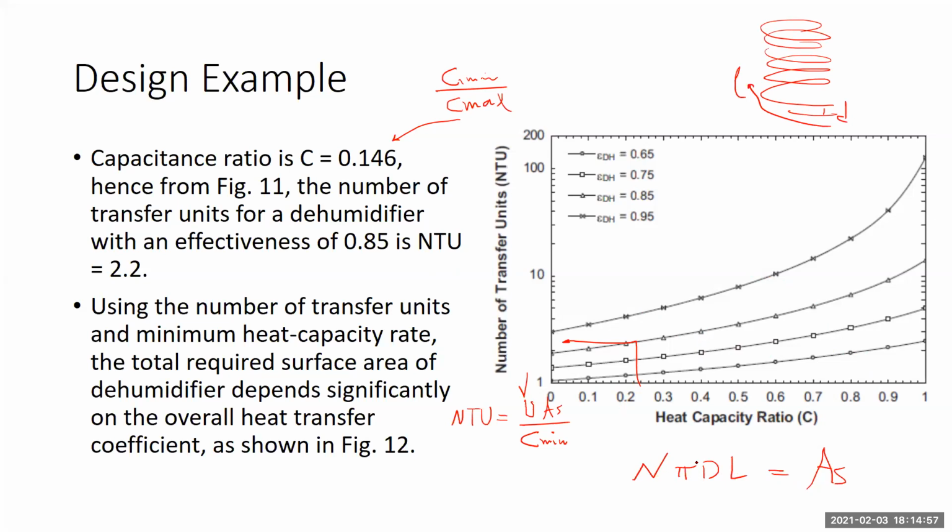And this is typically what we do, because normally for a condenser we prefer to use fin cooled units. You have a header here, another header here, and a lot of pipes in between, like the radiator of a car. And there is a fin system, or fin surface, so that you can increase the heat transfer rate as much as you can.